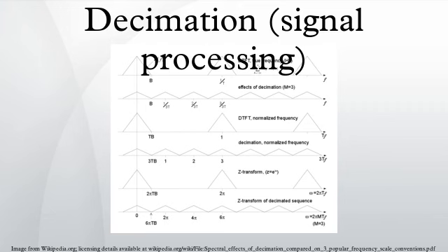Impulse response coefficients taken at intervals of M form a subsequence, and there are M such subsequences multiplexed together. The dot product is the sum of the dot products of each subsequence with the corresponding samples of the x sequence. Furthermore, because of downsampling by M, the stream of x samples involved in any one of the M dot products is never involved in the other dot products.